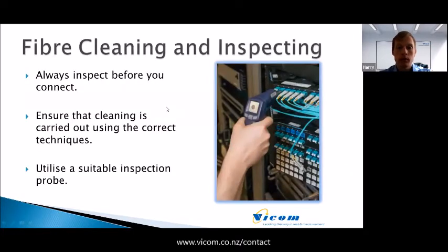So just summarizing on fiber cleaning and inspecting, it's absolutely paramount and critical that you always inspect before you connect, or clean, inspect before you connect. Ensure that cleaning is carried out using the correct techniques. If you don't use the correct techniques or use improper techniques like wiping on your shirt, you could either make it worse, or you can also cause damage on connector end faces, which will obviously then require replacement and troubleshooting at a later point in time.